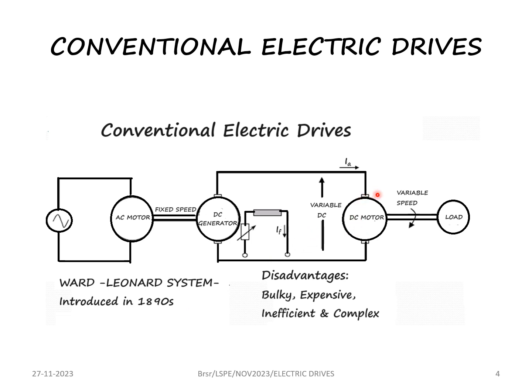In this case, if the speed of this motor is to be controlled, the supply voltage to this motor should be changed, and the input voltage for this DC motor is given from the DC generator. If the DC generator develops different voltages, the motor's input is also different, and so it will run at different speeds. The DC generator requires a mechanical input.